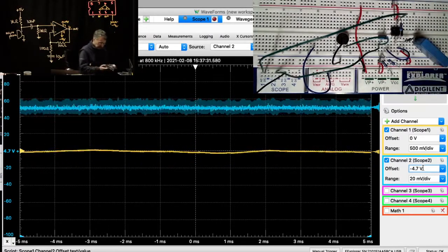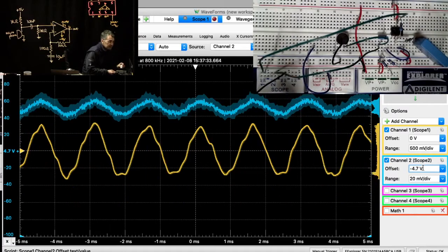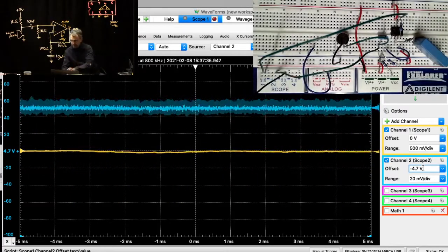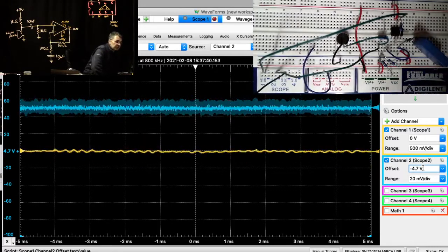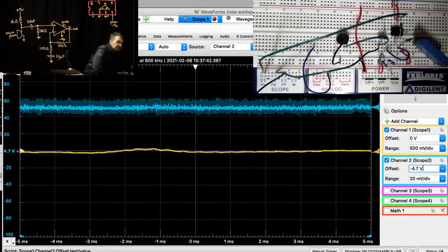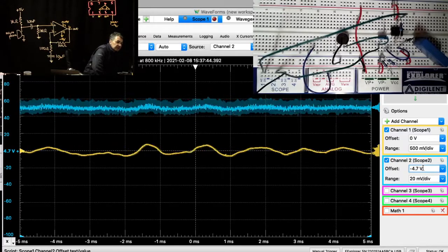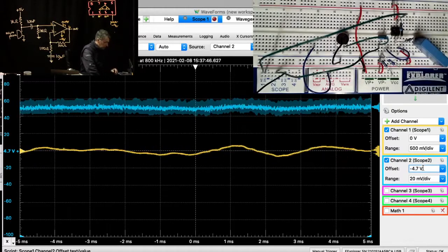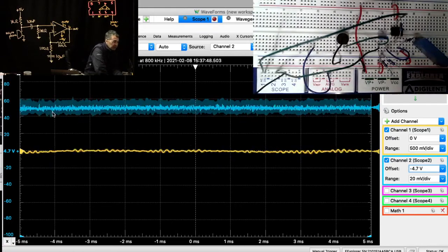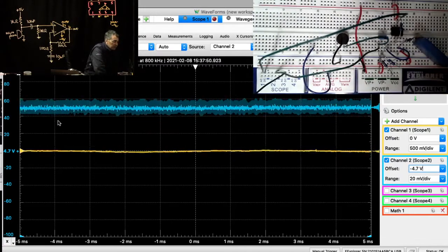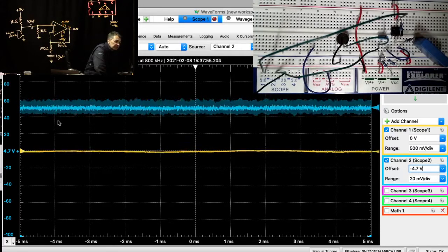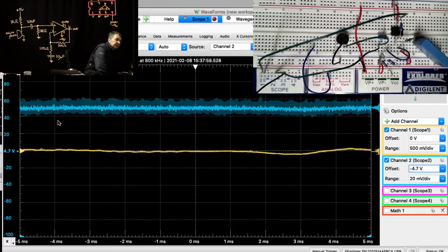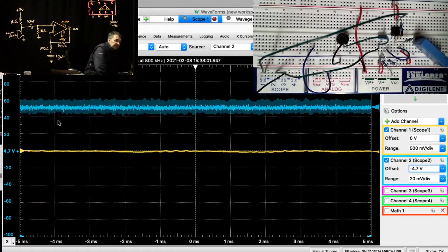I don't know if the doorbell is going to help. Well, okay. So you can see that we're turning a pretty tiny signal into a signal about 100 times bigger. And you can see that in order for the microphone to work properly, it requires this big DC offset close to 5 volts. But we don't want that to go into the op-amp, so that 100 nanofarad blocking capacitor takes care of that.